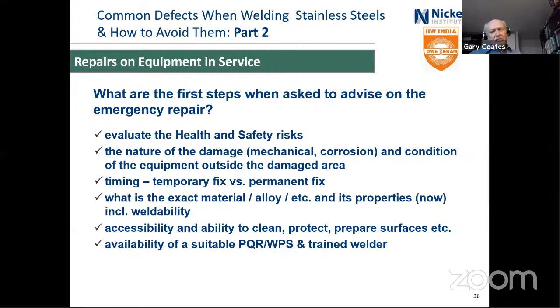And the properties, what the properties are now. So if it's been in high temperature service, the properties of the material may change. So a lot of alloys meant for high temperature, whether it's 309 or 310, they may actually start to become brittle with time, depending on what the temperature is there. So they're very soft and ductile when they're put in, but they can become brittle. And weldability will be very, very different.